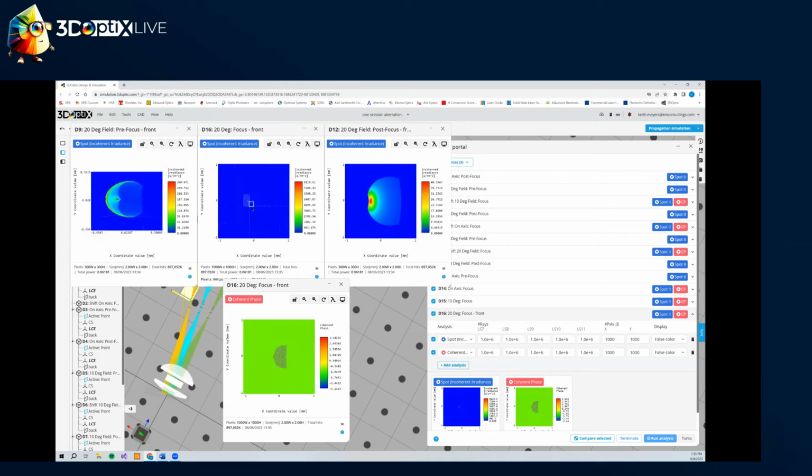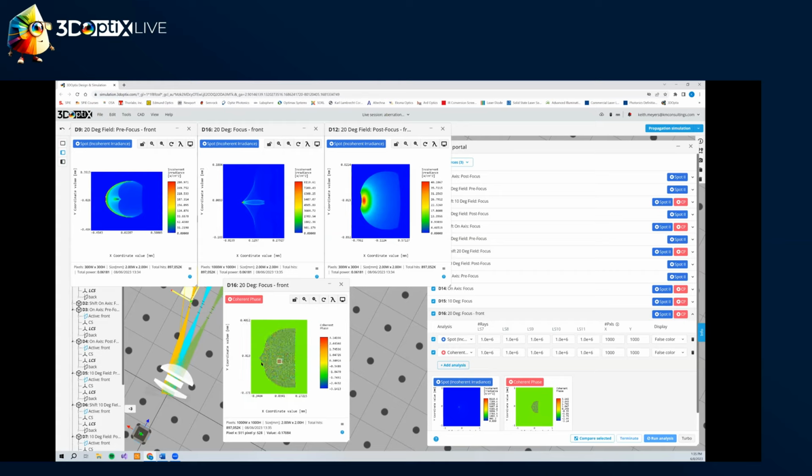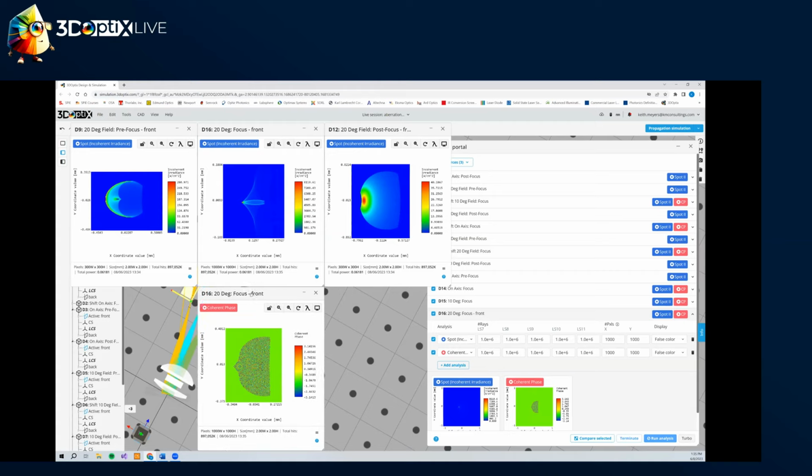All right, so we can physically see from the spot diagrams that we're having an aberrated beam. And then the phase plot is definitely aberrated. We're seeing a little bit of that coma and other aberrations here as well. Okay, great. So again, this is a good way to get a visual basic analysis of the aberrations in your system. Having an on-axis and some off-axis beams, we can definitely see that there are aberrations in the system. Kind of a quick check.